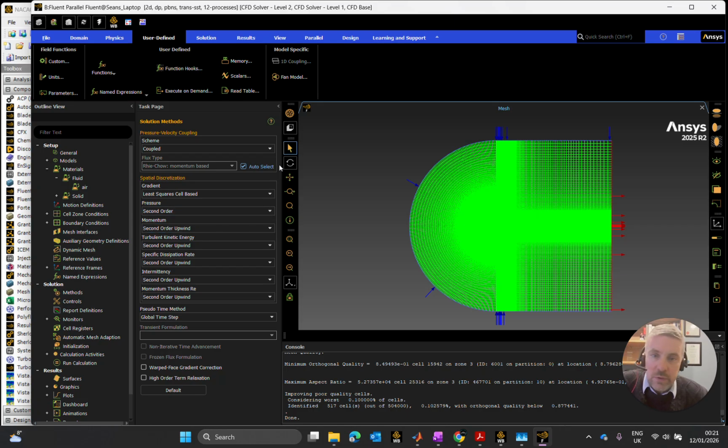But again, the ANSYS Fluent users guide will give good guidance for the likes of an external flow application for airfoils at these lower Reynolds numbers, or where you're at transitional flow and using a specific turbulence model, which ones lend itself to it. I tend to always start with the coupled one anyway, and we'll see how we go with that one.